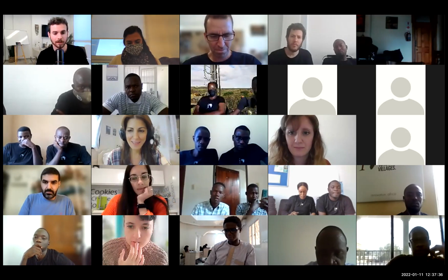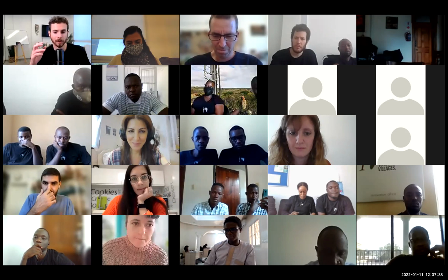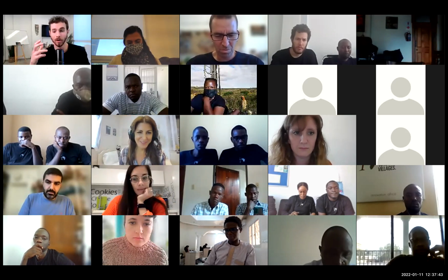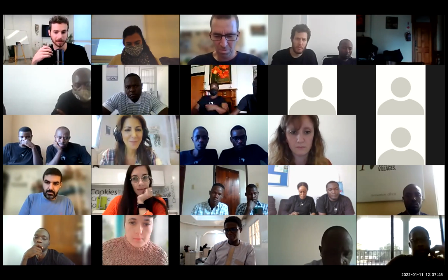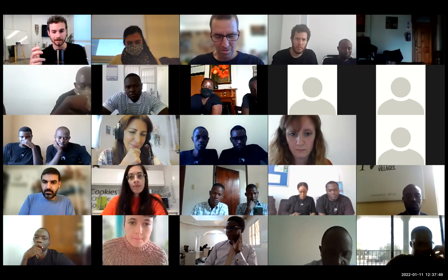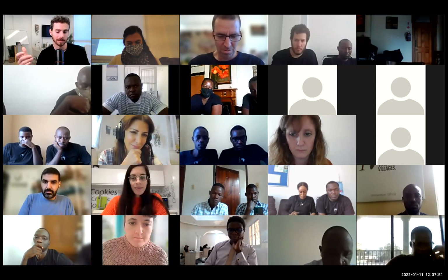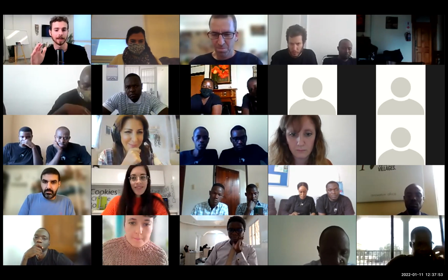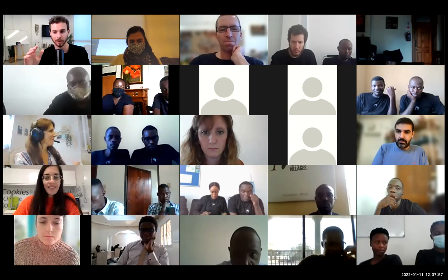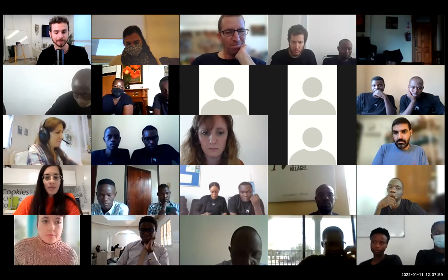Another thing to note is that once we get the data from Grundfos, we don't go blindly and just choose the solar panels. We need to also do all the calculations by ourselves. So we don't rely on Grundfos. We just take the recommendation they give us. But after that, we're going to go on the data, just like I showed you, and select the quantity and all the specifications by ourselves. So that's a right question.